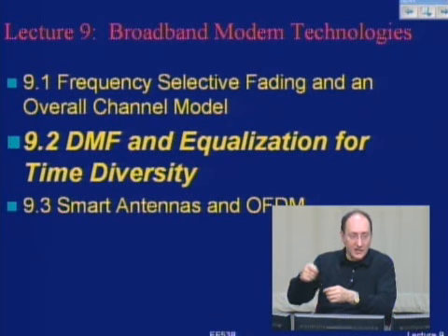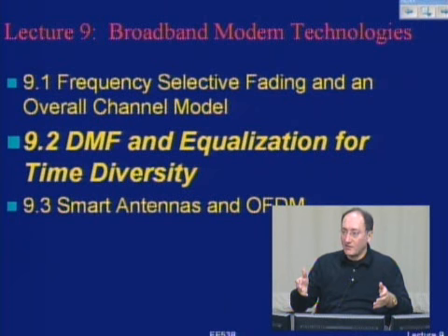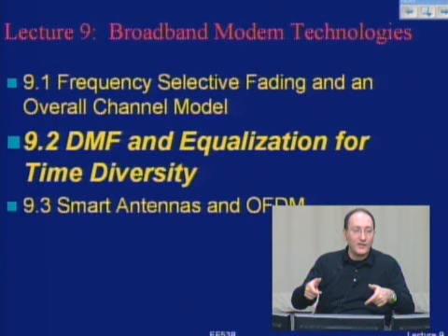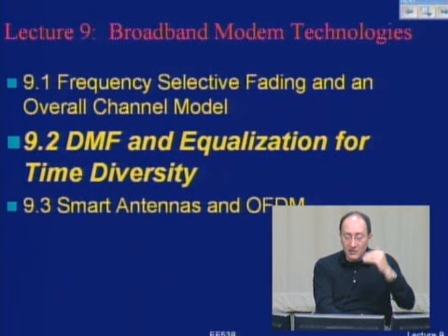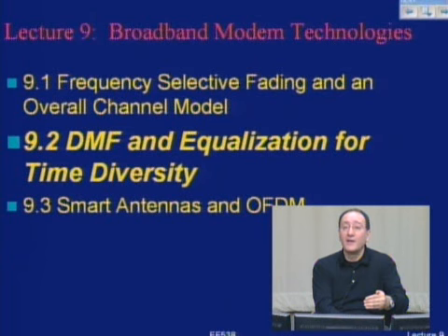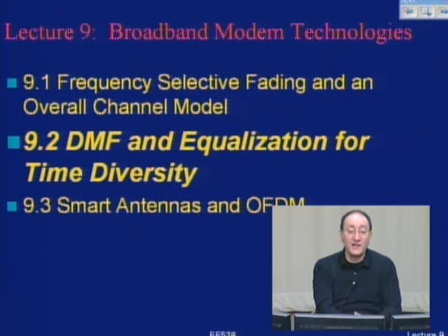Those samples you're receiving really are the output of an FIR filter. And the taps of that FIR filter are fading taps. They are not fixed, they are changing. This is what I told you for the channel model. Having that channel model in the back of my mind, when we come back, I'll tell you how we can exploit it to do discrete matched filtering and equalization, which I refer to as time diversity.